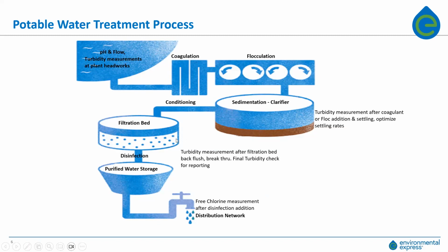The filter bed is made of coarse gravel, fine gravel, sand, and the most important component, activated carbon. The activated carbon does a great job in reducing fines or small sediment particles. Some ionic species are removed as well. Once it passes through the filtration bed, you want to have a level of 1 NTU down to about 0.5 NTUs. That is fairly clear water, and it won't interfere with the disinfection process.